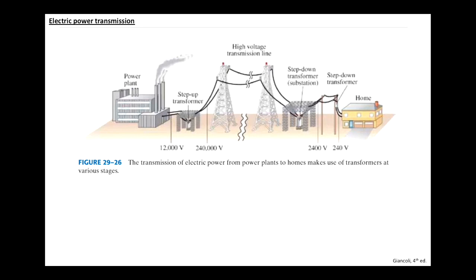And if you think about passing that through miles of cables, even if they have a really low resistance, that resistance adds up as the wires get longer and longer. If I just say someone over there is going to need 10 amps, let's just send them 10 amps. That 10 amps has to flow for miles and miles. It's going to pass through all that resistance. The wires are going to heat up, and I'm going to lose a lot of energy in the process.